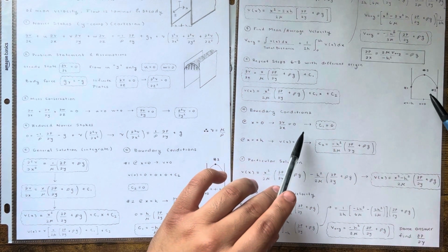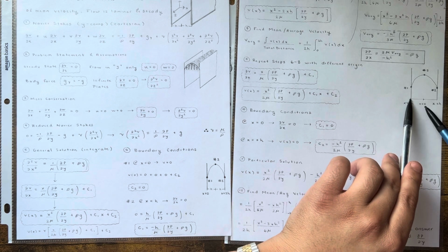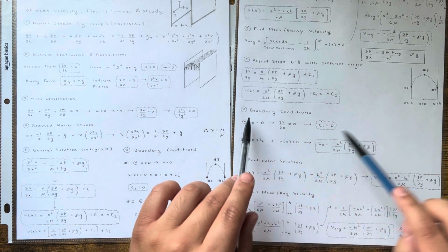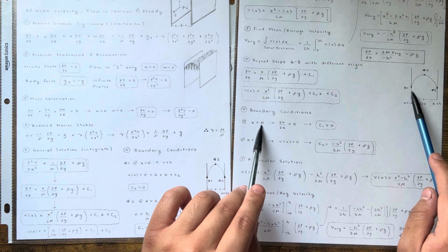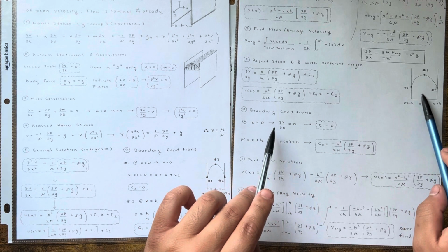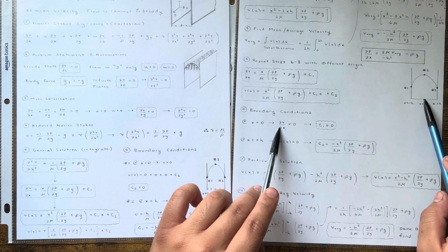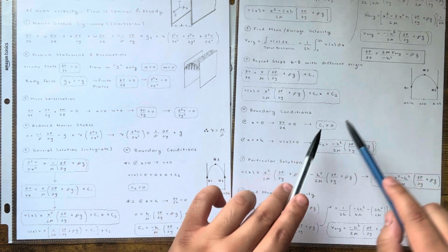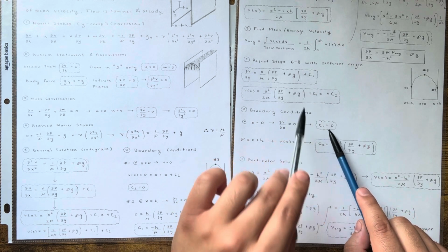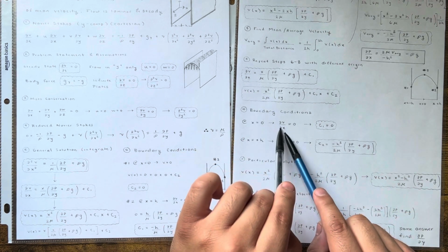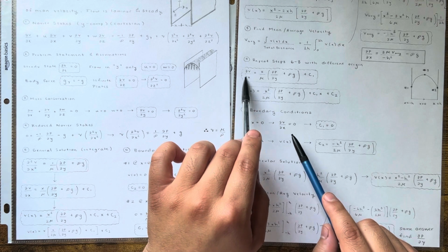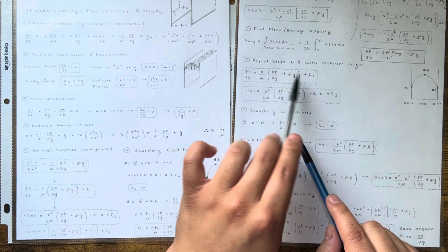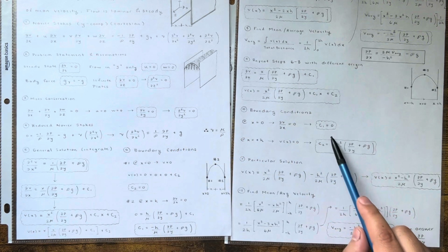Now I'm gonna apply boundary conditions. I got x equals negative h, x equals 0, x equals h. So at x equals 0, we know the change in velocity is 0, I'm sorry. So right here, down the middle, x equals 0, change in velocity is 0. So that means my C1 is 0, right? Because I'm going to use this equation, change in v over change in x. So this is 0. For any x you see, plug in a 0. So this is 0 times all this, which is 0. So C1 is 0. Boom.